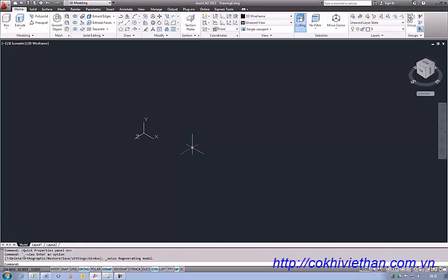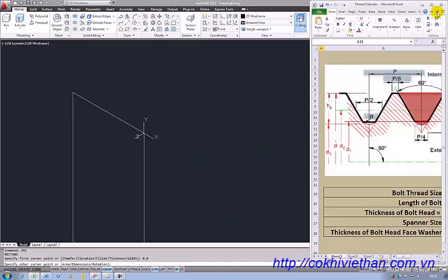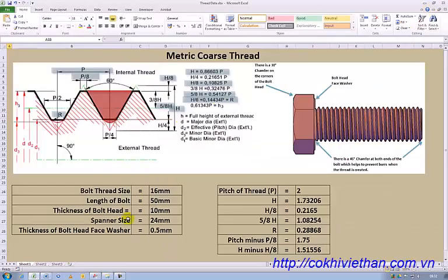So we're going to start by typing in rectangle, so REC, and as we can see AutoCAD has auto-completed it for us, so I'm just going to click on there. Right, it's asking us for our first corner point, so we'll start at 0,0. So let's type 0,0 and hit enter. And our next coordinates, well, what we can do is, if we have a look back at our Excel spreadsheet, we know that our bolt is going to be a 16mm bolt, and we know that the length of it is 50mm long.